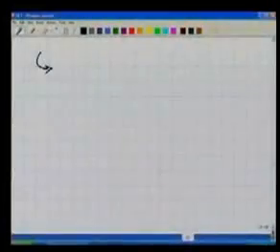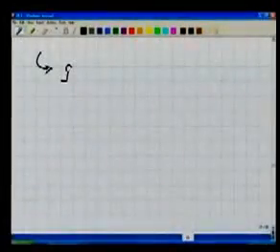We saw just now a simple procedure of taking the observation for this angle ABC by observing the readings on the verniers and taking their difference. But what is special about this method of repetition? So we'll talk about that now. In method of repetition, we try to achieve some extra things. Number one, we increase the precision.